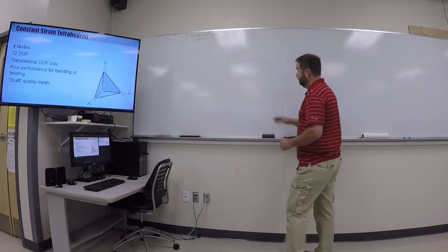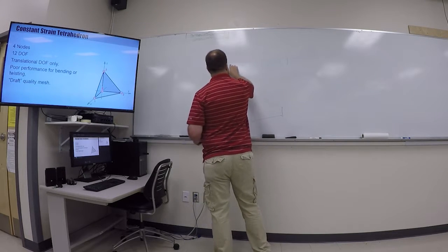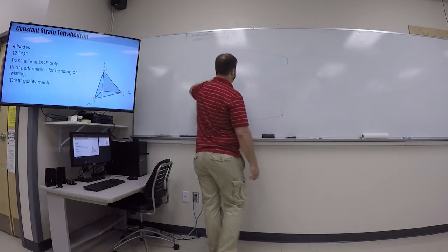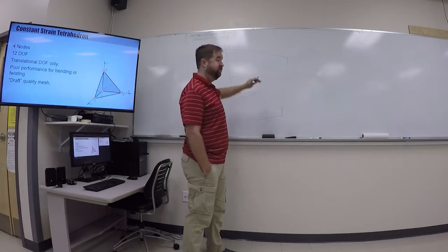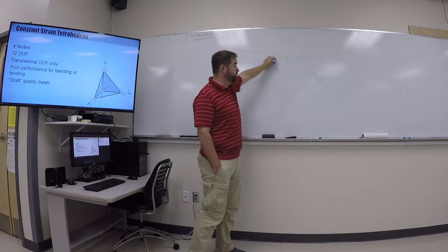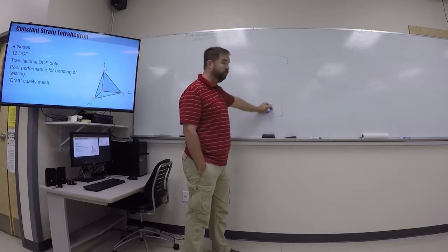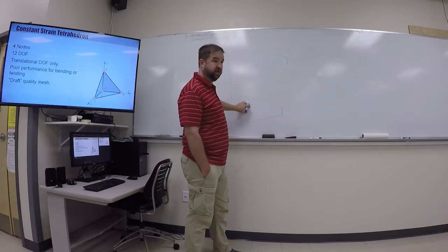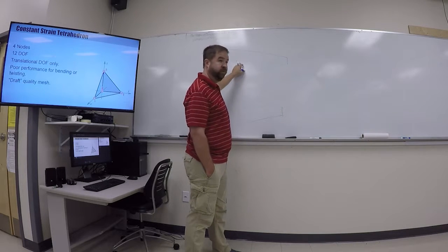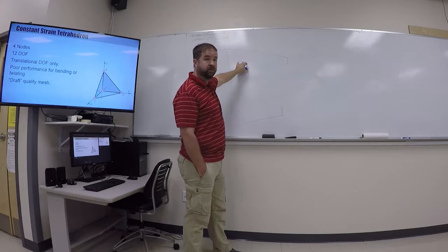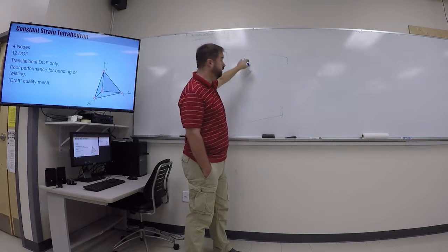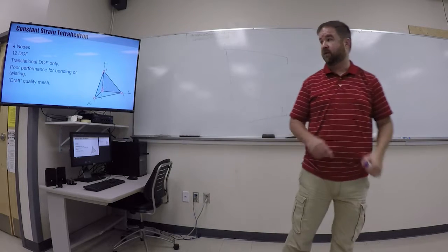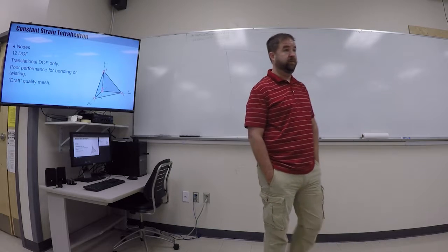Let's say now, though, that my tapered beam is tapering in the vertical direction as well. So just to keep something simple, now I have a tapered beam that is different thicknesses as well as different widths down its length. I'm not going to be able to capture that with shell elements because my thickness is different in different areas of my model, and so I can't use two-dimensional elements. So this I would have to go to a three-dimensional element.